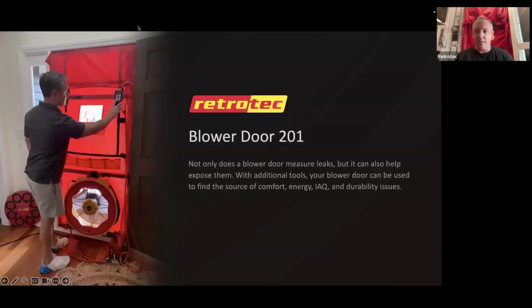This is probably one of the most requested webinars we've had: once you get your blower door reading, what's next? How do I actually identify where the leaks are, where the comfort problems are, and then move forward? In this webinar, I'm going to show you a few different ways to do that. Pretty much all of them require your blower door, plus some additional tools to make those air leaks visible. That's one of the hardest things about what we do: we're chasing down something invisible.